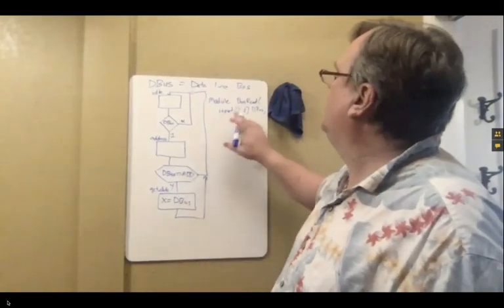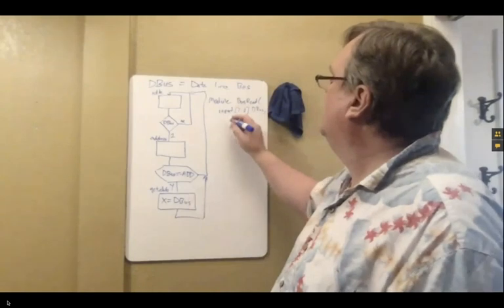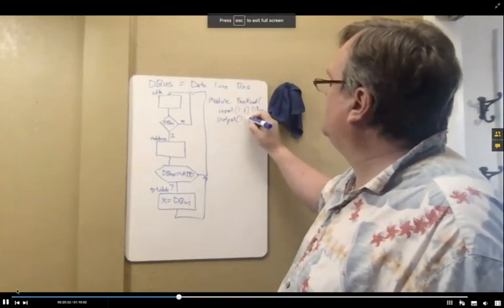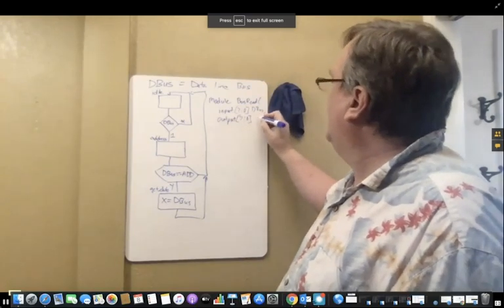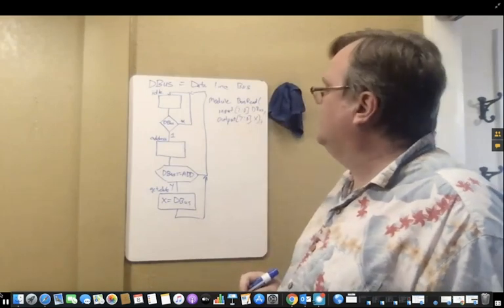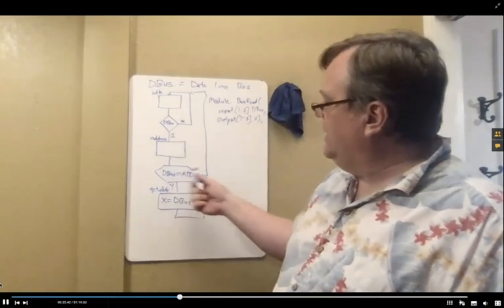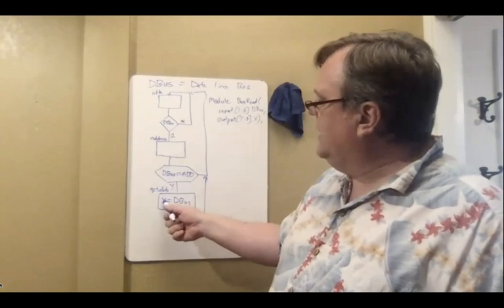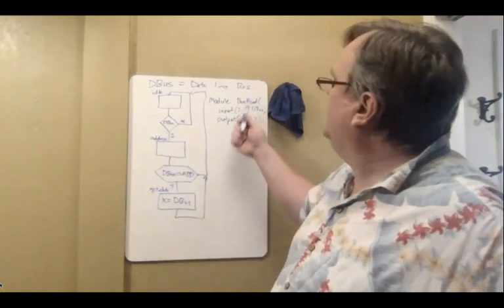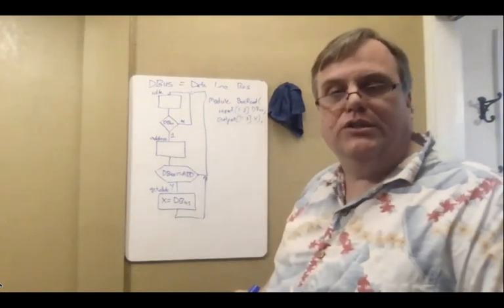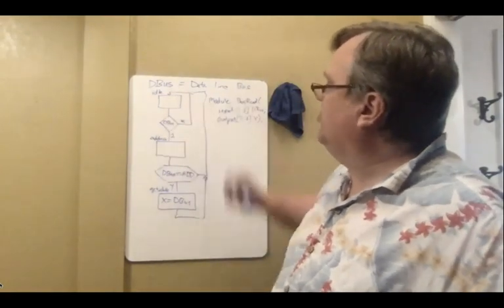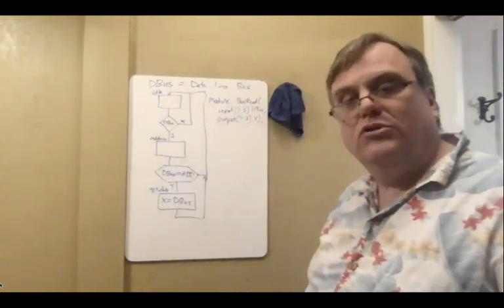My whole job here is just to do the bus read. So my output is also 7 down to 0, and it's my X, the data that I read. So I can look at this and see things that I'm sending out and things that I'm reading and using internally to determine what their function is inside my module. So that's step 1. I determine my inputs and my outputs.